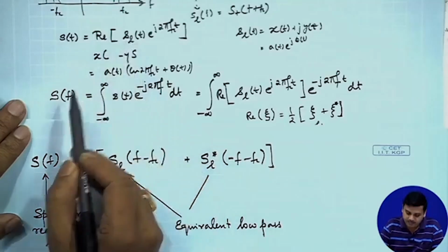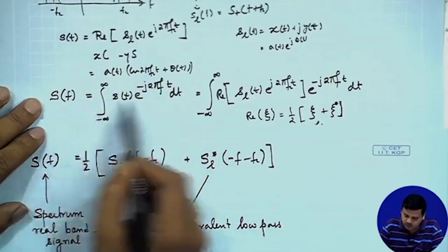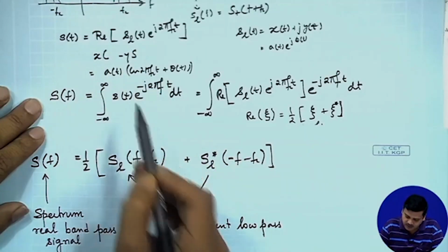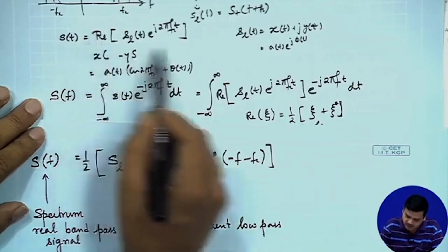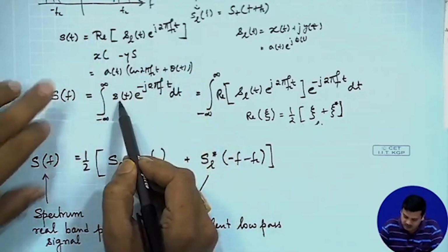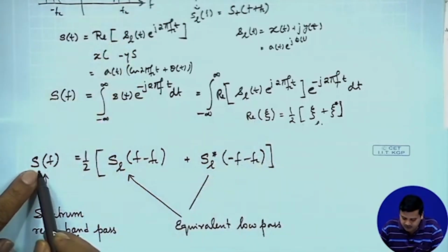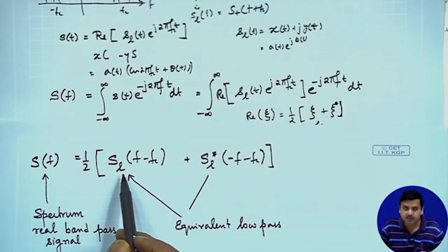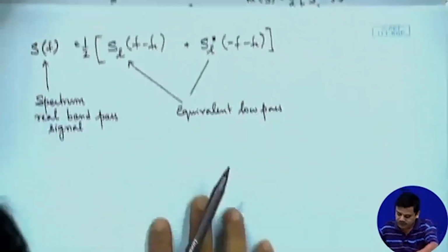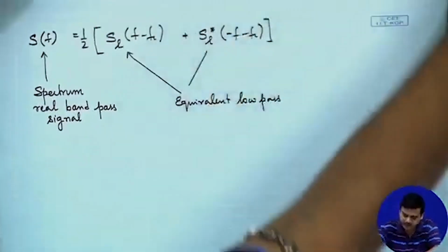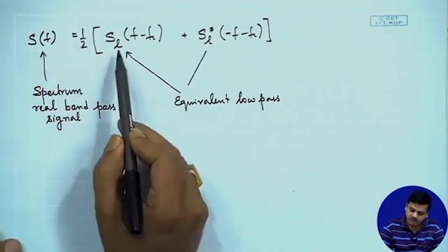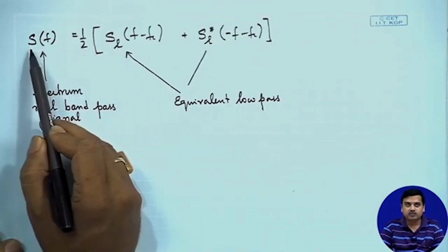s(t), s_L(t), S(f). Now, what we want is a Fourier relationship of this, and s(t) we have represented in terms of s_L(t). So, from s(t) we have gone to its low pass equivalent, and then we could connect the spectrum to its low pass equivalent. So, thereby again we are saying that if we have the low pass equivalent, then it could relate to the pass band.